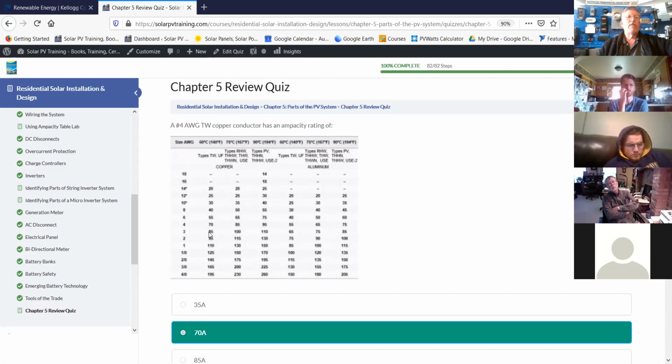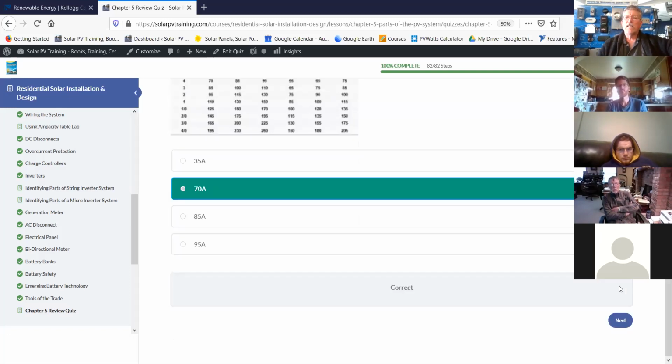So just to be safe, because you don't necessarily know what equipment is being connected when you're sizing the wire, or you may swap out that equipment in the future, you should make it a habit of always just looking at column 1 to select the ampacity rating of your wire. So even though you're using a high temperature wire, still size it as if you were using a low temperature wire, because you don't know what those terminal ratings are going to be. And that's something that people, even very experienced installers, get messed up with when they're out in the field sizing this stuff.